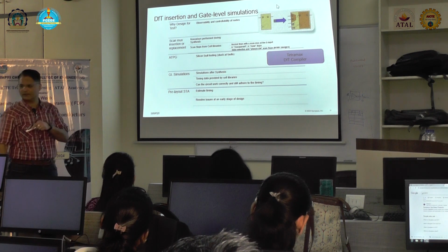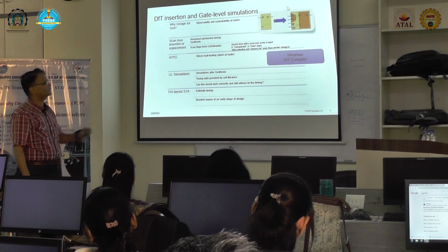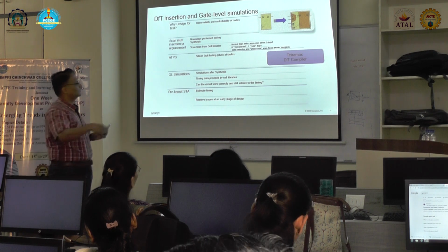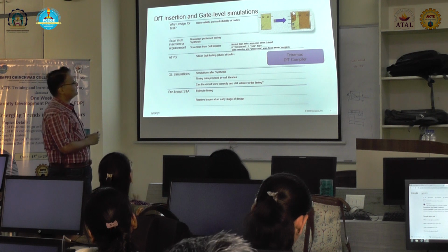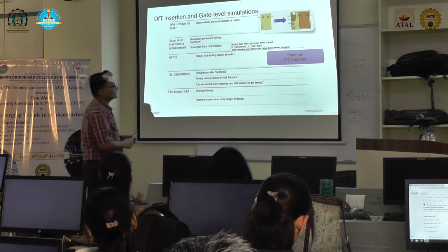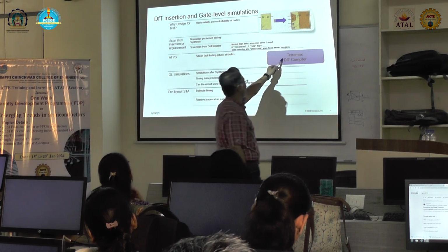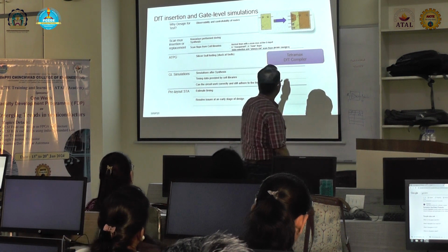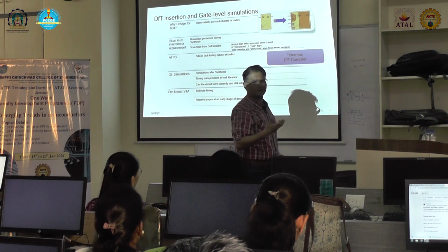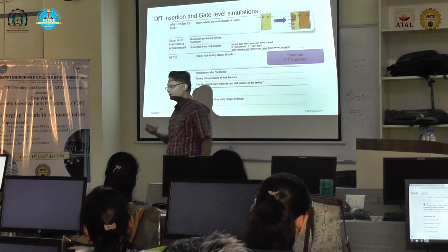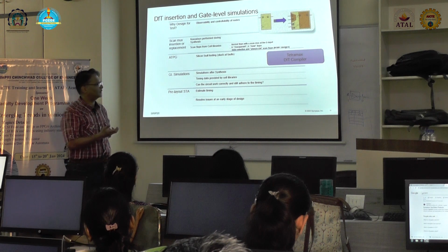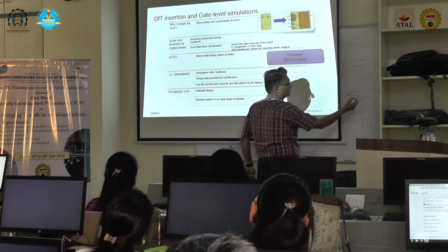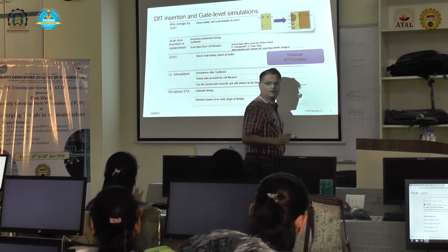Okay, so does that answer your question? What is the difference between ATPG and DFT? We have Tetramax and DFT Compiler. Tetramax is the tool which helps us generate the ATPG vectors, as I said. It reads in the netlist and generates this truth table: 0, 1, 1, 0.